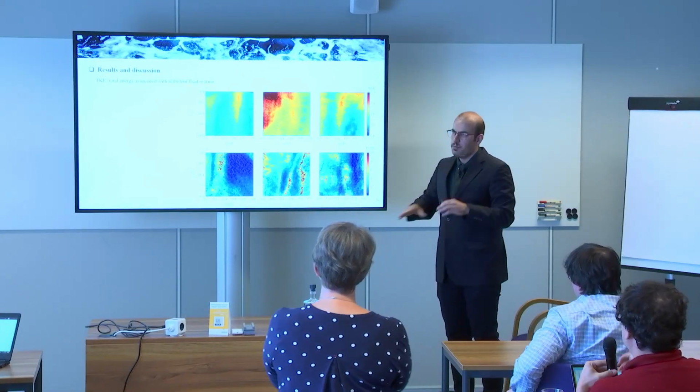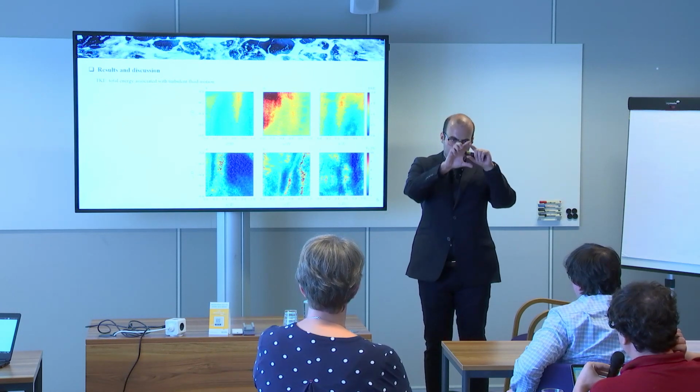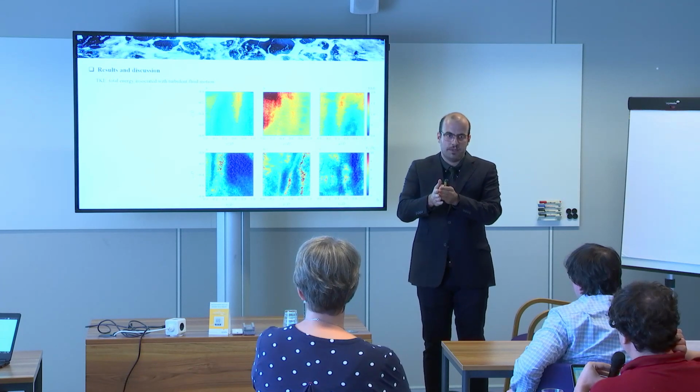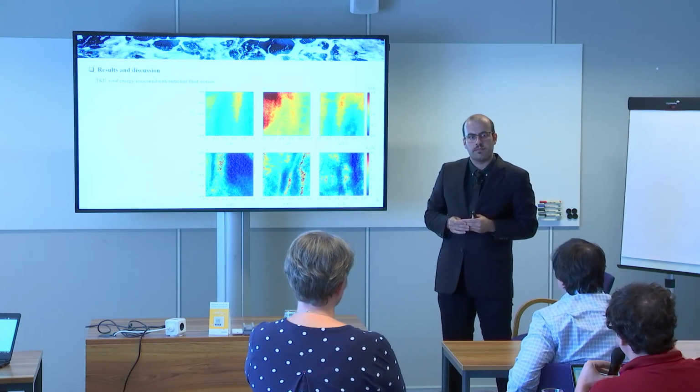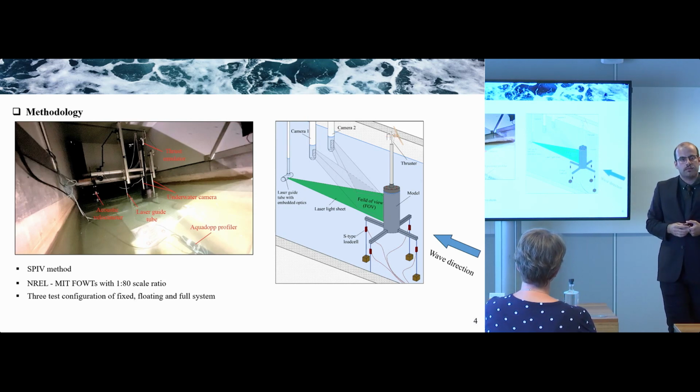Yes, true. The PIV window, the maximum window, was about 30 by 30 centimeters, but we of course lost a bit of the corners because we need to align it based on the calibration plate. But I mean the windowing for the correlations when you run the PIV algorithm, the interrogation window. So you mean the field of view here? This field of view. So that in the post-processing, you divide it into small interrogation windows that tend to be 16 to 32 square pixels? Oh, you mean the post-processing.